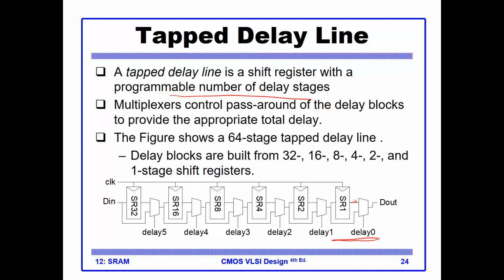And then the output of this goes into a multiplexer, and the multiplexer has two inputs, one coming from the shifter and one bypassing the shifter. By activating this control signal, I either take the delayed cycle of one cycle or no delay. So it depends on the value of this, 0 or 1.